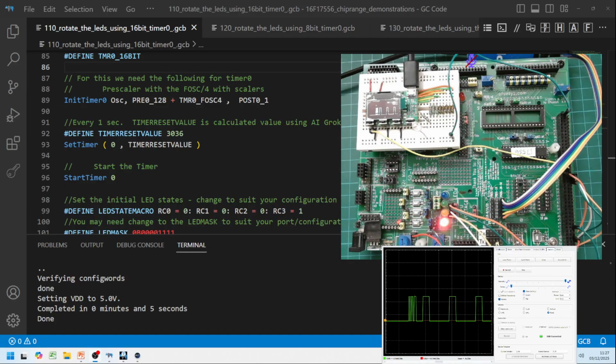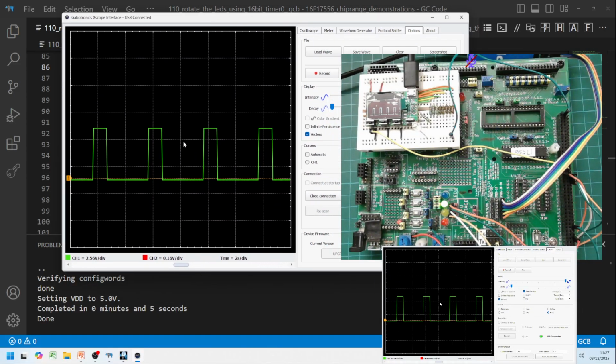What we've got is the oscilloscope showing us every time the blue LED goes high. If we zoom in, I'll bring it up so that you can see it on this big screen here. Look, the division in here is every 2 seconds. So if I look at the divisions, I've got 2 divisions. That means every 4 seconds. But I set it to 1 second. Of course, it's every 4th LED, every time the 4th LED comes up. So we now know we've got 1 second.